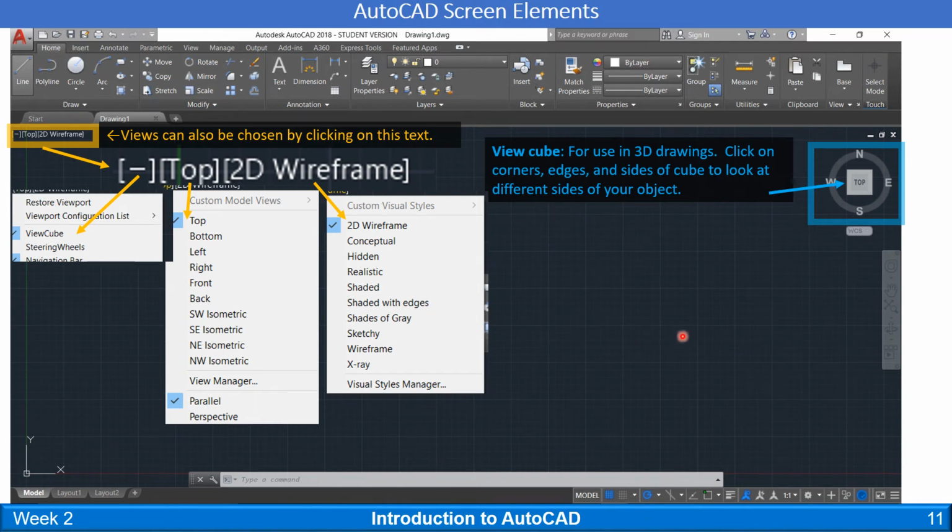Okay, so let's talk about how to navigate around in your drawing area. There's a couple different tools over here to use. One is the ViewCube, and you can grab this ViewCube and click on the corners, the edges, and the faces, and it's going to reorient your drawing object to go with those corners and faces.